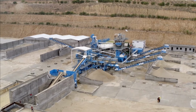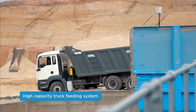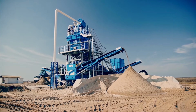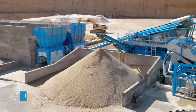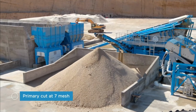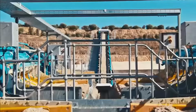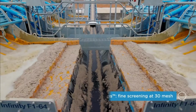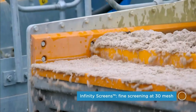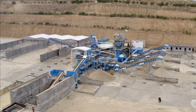The operation begins with dump trucks unloading crushed silica directly into the feeding system. This mechanism controls the input into the wash plant. The sand is then pre-screened to eliminate any large particles using a primary cut of 7 mesh. The term mesh describes the number of pores per inch. For example, the 5 infinite high-frequency infinite screens cut sand at 30 mesh, which means there are 30 holes on each inch of the screen. Only sand particles of a specific size can pass through these openings when vibrated. This method separates coarse sand and stores it for use in building.